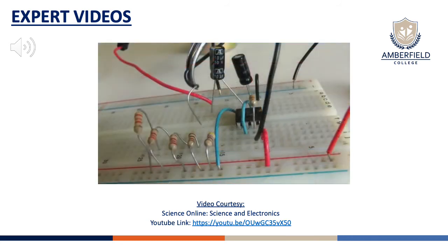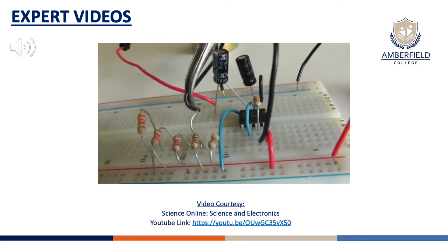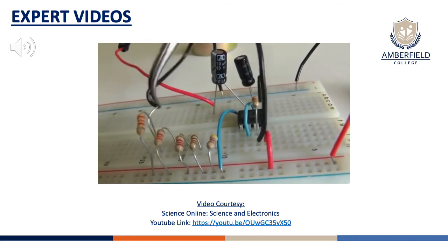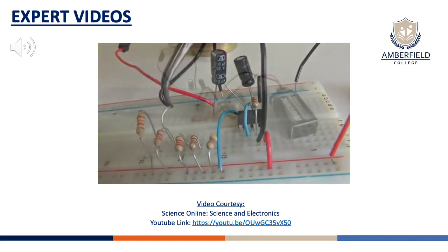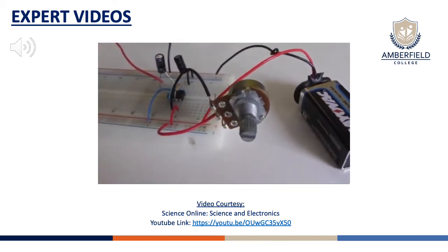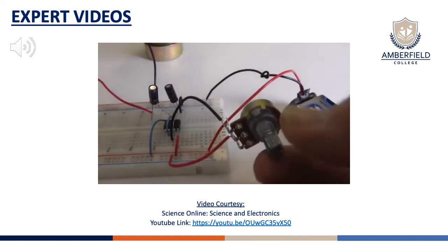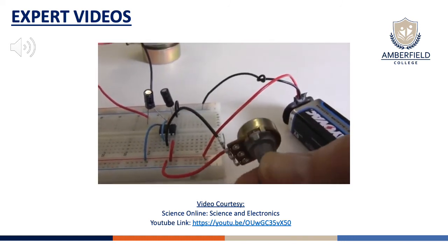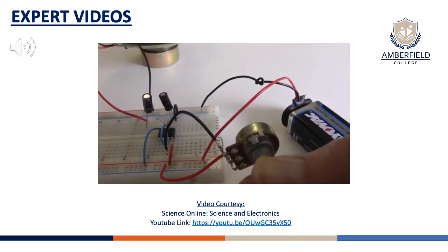You can create a simple keyboard by connecting a string of different resistors along the positive supply line. Remove R2 and connect a wire to pin 7. Connecting the other end of that wire to the resistor creates this sound. This is a potentiometer, a variable resistor. Turning the shaft produces a resistance from 0 to 10,000 ohms. Using it in place of R2 produces this tone.